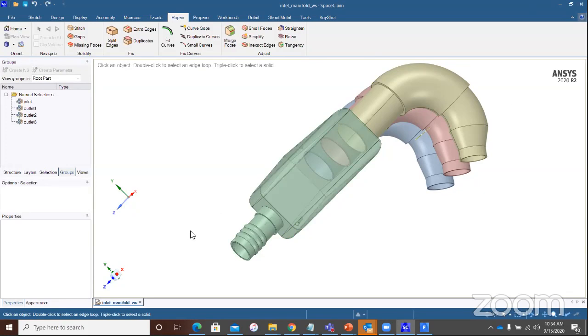In this case, I would do that because this is a pressure manifold. For example, if this were for a charge airline, the pressure is not that high. If it's around 3,000 Pascal or 4,000 Pascal, for a certain kind of engine, then you don't want to use a wrapped mesh around this geometry because it might not be accurate. So you have to decide in which case would you compromise on the exact accuracy of the geometry to get directional answers for your CFD simulations. If your velocity or pressure values are too delicate, too sensitive based on the geometry features, then stick with watertight geometry meshing. If it's something that won't probably vary if you de-feature a certain edge, then go with fault-tolerant meshing.